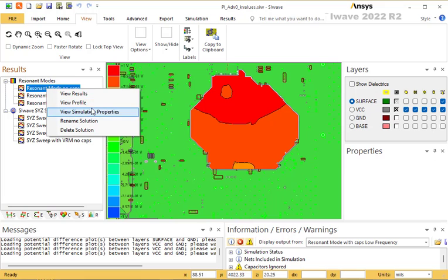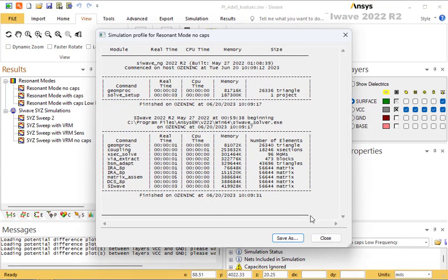There are other things that you can do. Look at the profile, of course, which will tell you more information about how much time was spent and the mesh size and all of this information. These are important when you are comparing the solution of two models, or you are comparing the solution of the same model at different times. It tells you whether the solver did something right, or whether the solution looked weird. It took, for example, a faster time to solve. That doesn't make any sense. It should spend the same amount of time if it's the same mesh.